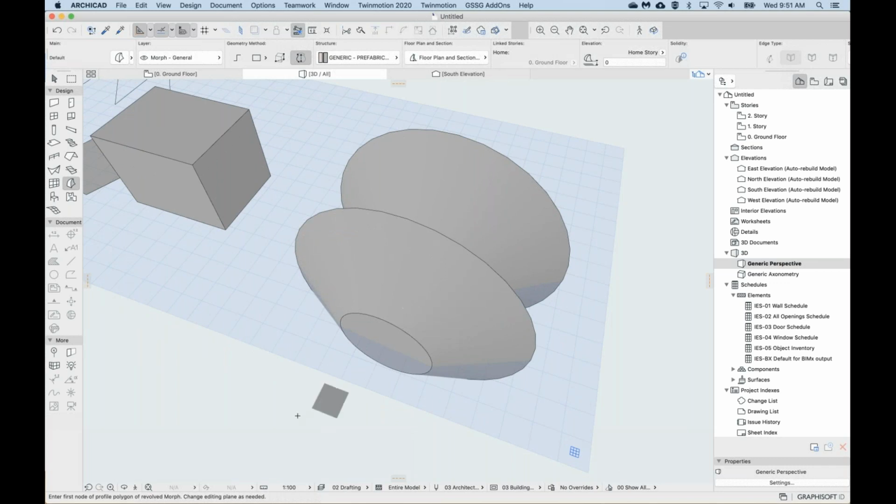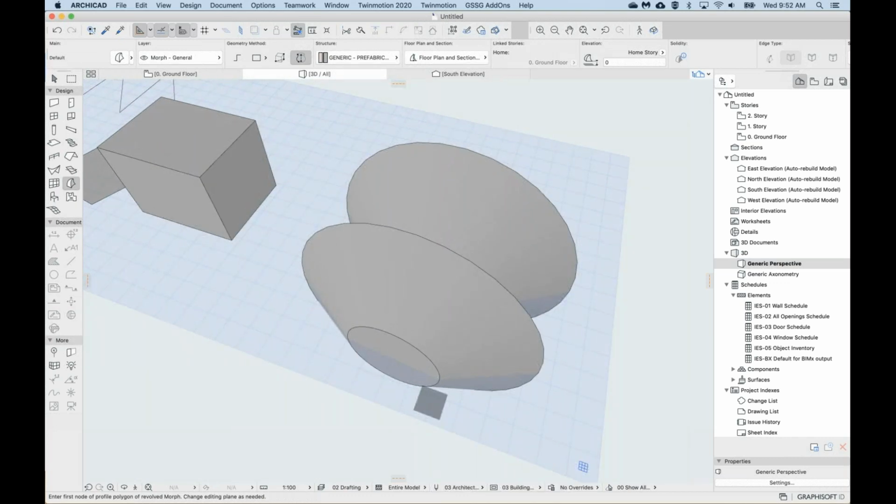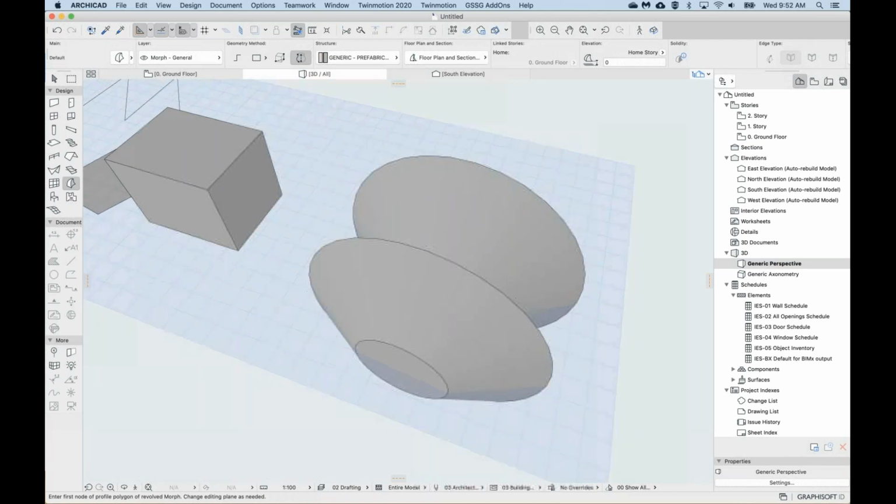When you finish a polyline, you can either do a second click on the last point to finish it, or, as I find it a little bit tricky sometimes, just right click and OK. So maybe this is easier, but either method is fine. The OK just finishes the polyline, because otherwise it will want to continue the polyline forever.